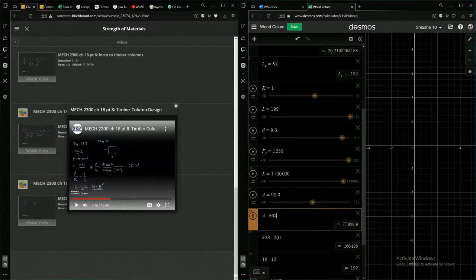I think we could go with a smaller beam. I'm going to try to be super efficient and grind this one out to get the perfect beam, because this is fun. I have a nice, easy, stress-free way to do this. So let's try a 6 by 6, so 5.5 on this.